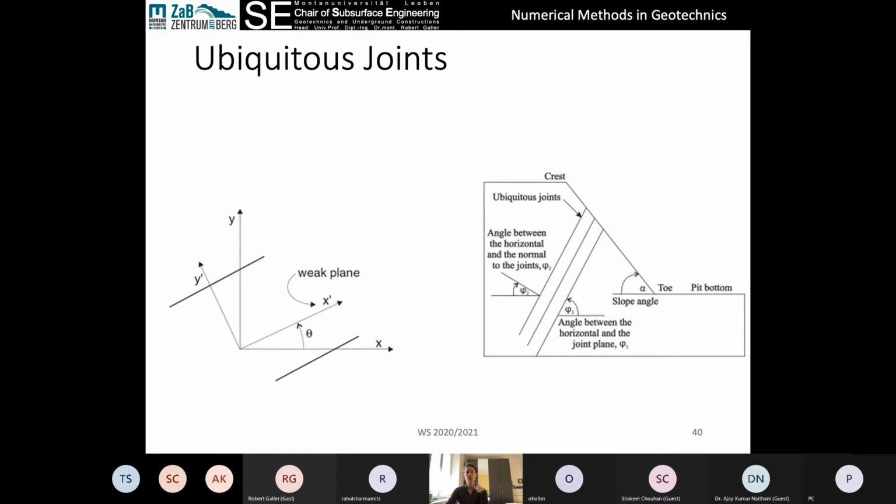The first time, it will solve the constitutive model, so failure or not failure, inside the element based on its failure criterion. So Mohr-Coulomb, generalized Hoek-Brown, Drucker-Prager, Cam-Clay, whatever it is for the material, it will solve to find out if that element has failed or not.